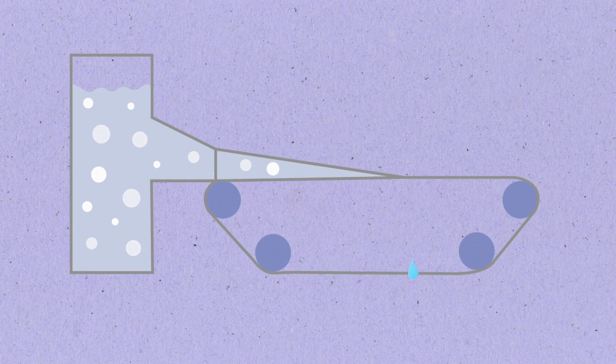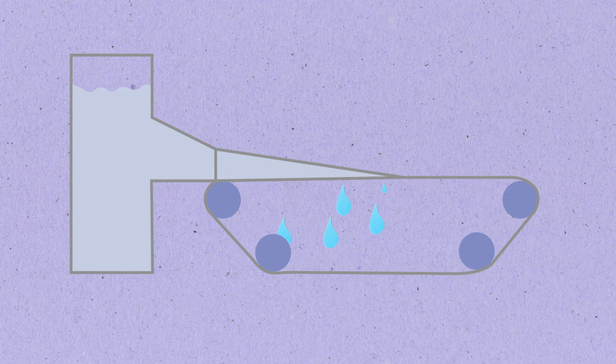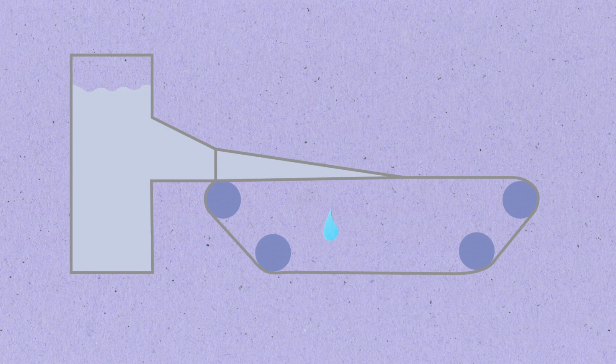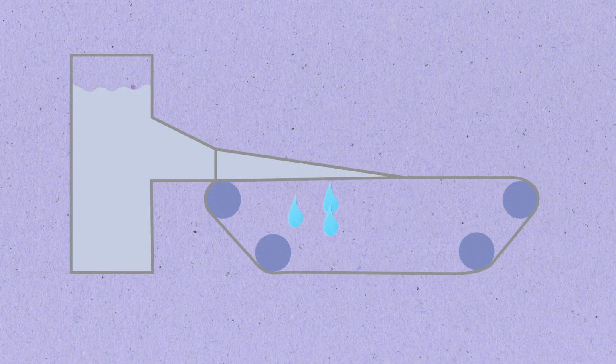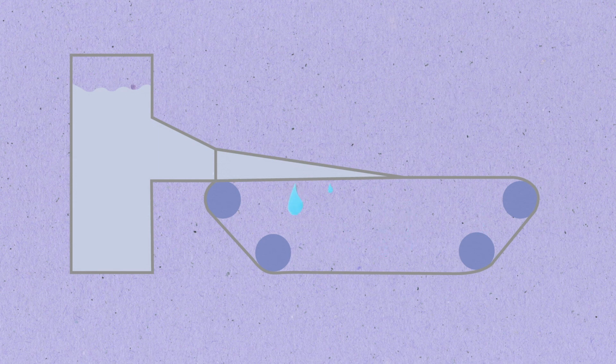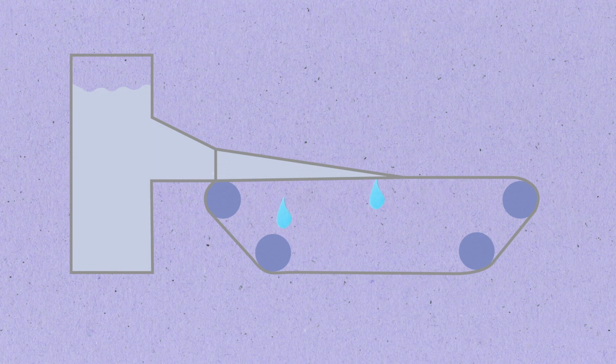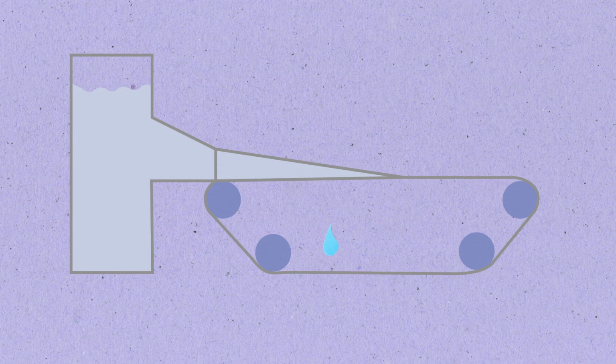The papermaking process is equipped with an air removal system. To ensure optimum deaeration, deaerator chemicals are used. Proper deaeration helps to prevent deposits in the system. If overdosed, they can be harmful to the process. If deaeration is poor, this can lead to problems such as pinholes, deposits, and pump cavitation.